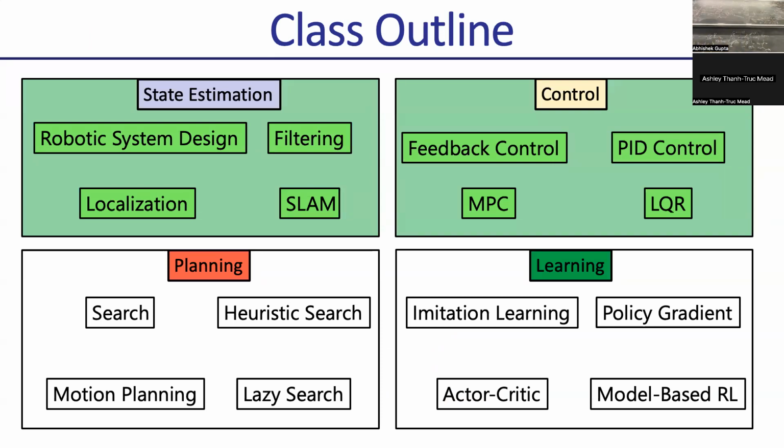state estimation, figuring out where the robot is in the world. Then we studied control and figuring out how to do feedback control so we can deal with disturbances. Right? And so the last few classes we covered feedback control, PID control, bang-bang control, LQR, versions of LQR, and then MPC. Right? And all of these are basically saying, you know, a path is given to you, how do you stabilize around that path? How do you follow that path without getting, you know, thrown off by disturbances?